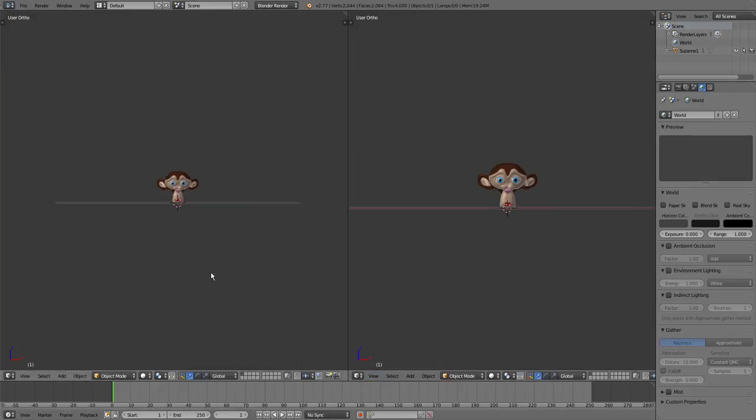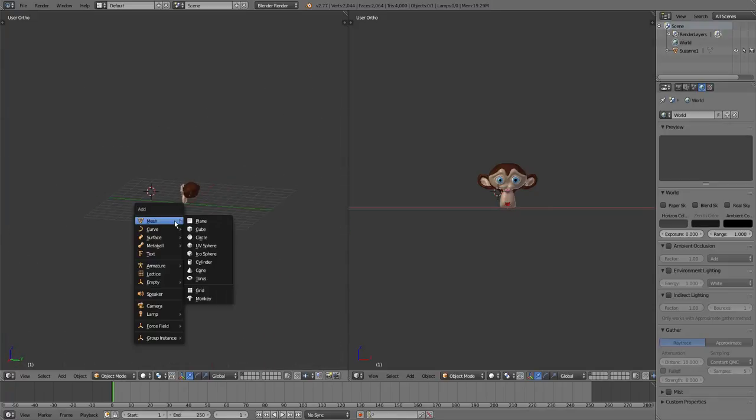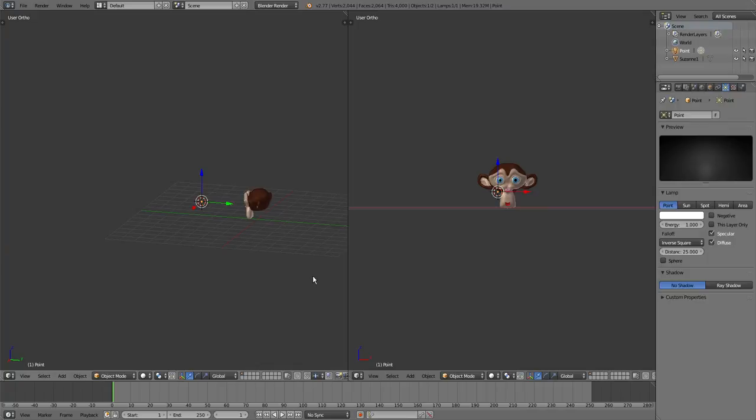So what I'm going to do here is go into rendered mode, but when you go into rendered mode, your scene won't light up unless you've got some sort of lighting in your scene. So I'm going to click over here and then Shift A and add a point light. Now a point light sort of just lights up this single point. You can change the energy of it, you can change the color. You can do basically all you need with the light. So now I can click here to view my rendered object.